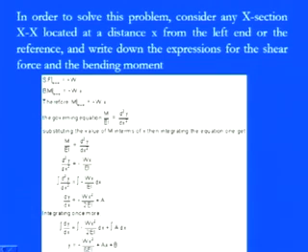Again, we integrate to get the value of the deflection. So, the integration of dy by dx is nothing but the integration of minus W x square by 2 EI plus A into dx. So, now we have the generalized deflection equation for a cantilever beam which is loaded at the extreme free end by a concentrated load W, which is y equals minus W x cube by 6 EI plus Ax plus B. So, this is a generalized equation. After putting in the different boundary values, we can get exactly what we want for the beam.